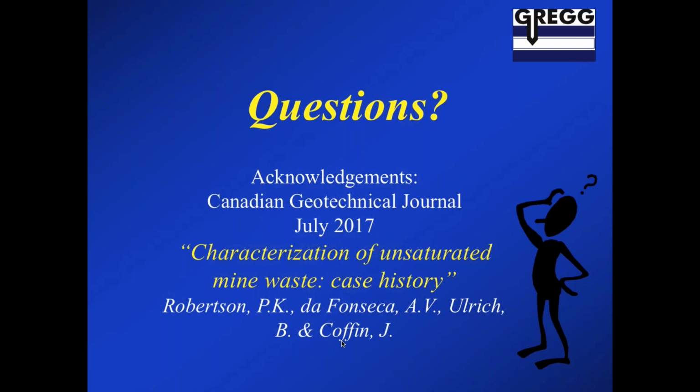Now, obviously doing MASW down to 100 meters is going to be challenging. You have to lay out the geophones to a very large extent. It's possible to do. The interpretation gets a little bit more approximate as you go deeper and deeper with surface waves, because you have to go to very long wavelengths. So it's pushing it a little bit to go to 100 meters.